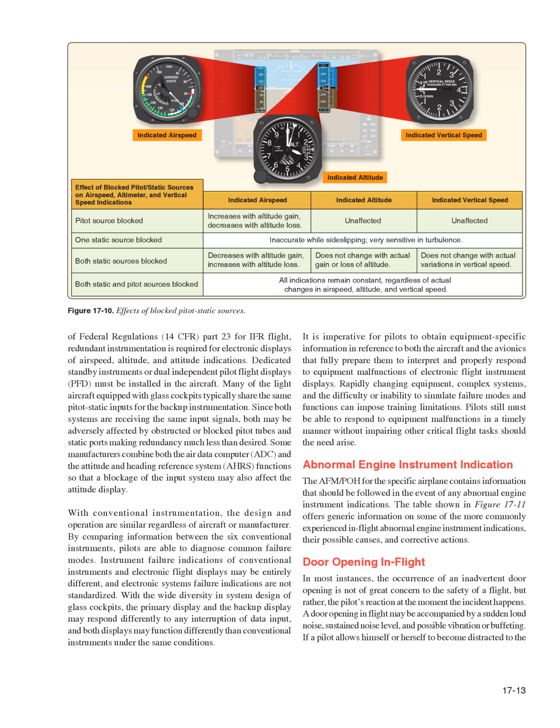Dedicated standby instruments or dual independent pilot flight displays, PFD, must be installed in the aircraft. Many of the light aircraft equipped with glass cockpits typically share the same pitot-static inputs for the backup instrumentation. Since both systems are receiving the same input signals, both may be adversely affected by obstructed or blocked pitot tubes and static ports, making redundancy much less than desired.